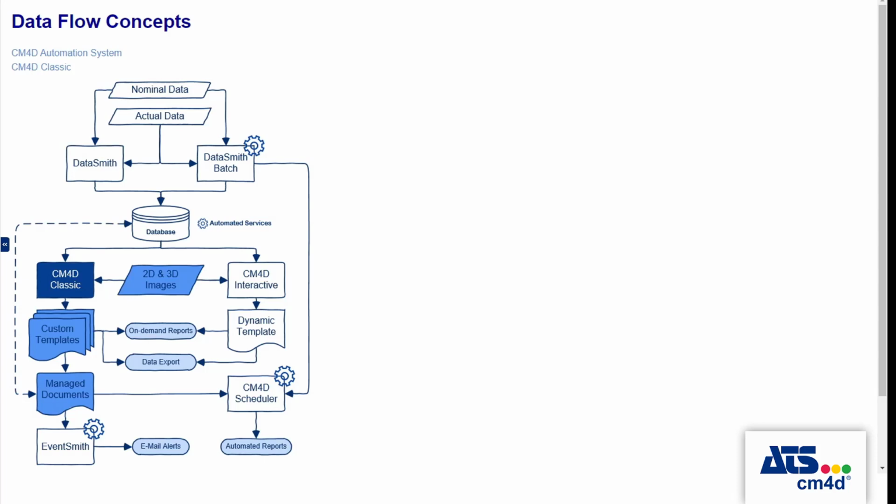So a translator is neither part specific or feature specific, but is format specific. So if you're measuring 10 unique types of parts like fender, bulkhead, side frame, roof, and other parts such like that coming from a collection device, say a CMM, or if you have a laser scanner, all you have to do is develop a translator based on the output from that laser scanner or that CMM, and then that one translator can be used for anything that you measure on that collection device, and for any part coming off from that collection device.